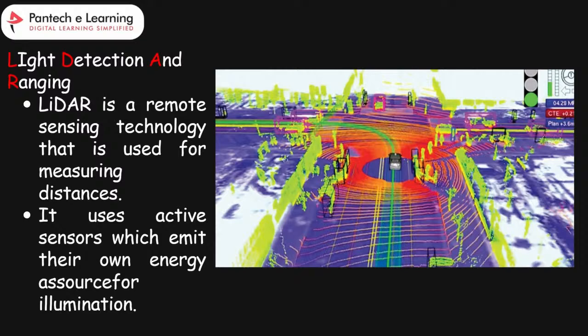And this Lidar sensor spins around continuously, kind of like a spinning top. They shoot out thousands of tiny laser beams every second. This is a diagram of the Lidar. These laser beams go out in all directions around the vehicle. They hit objects in the surroundings like buildings, trees or other cars, and when they hit something, they bounce back. By measuring how long it takes for the laser beams to bounce back, the Lidar can figure out how far things are.